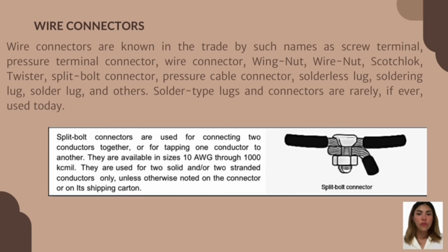In fact, connections that depend on solder are not permitted for connecting service entrance conductors to service equipment. Solder is also not permitted for grounding and bonding connections.